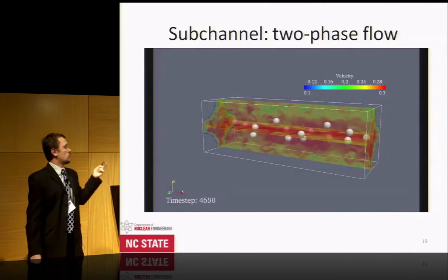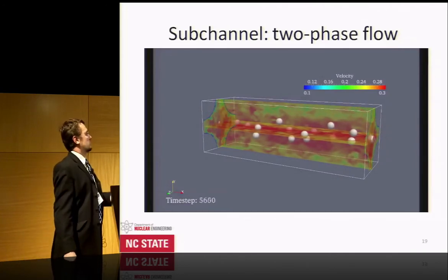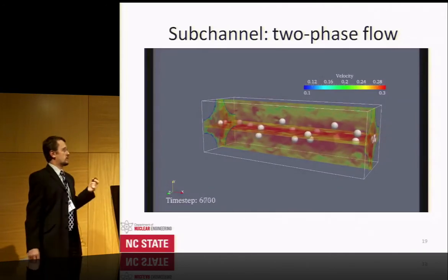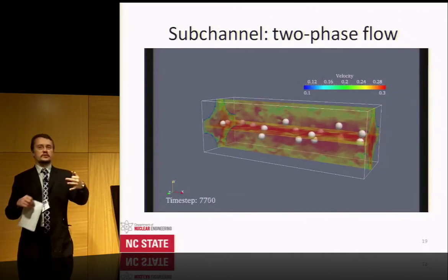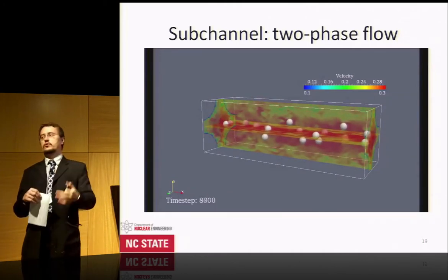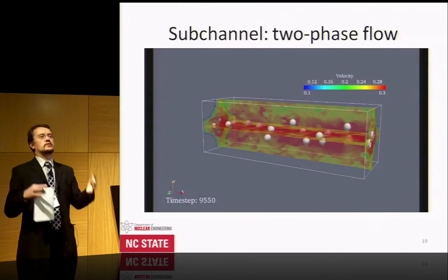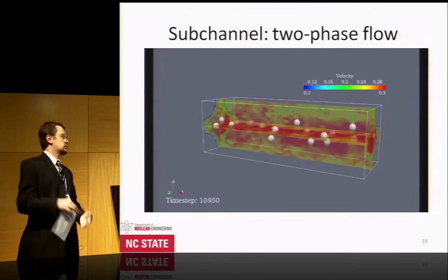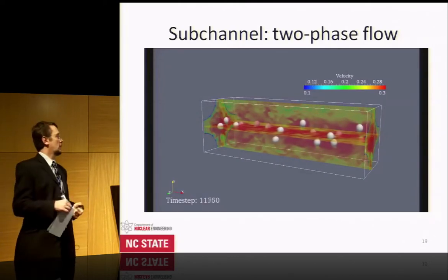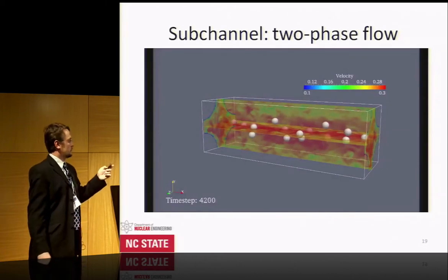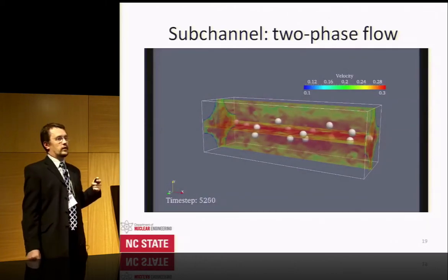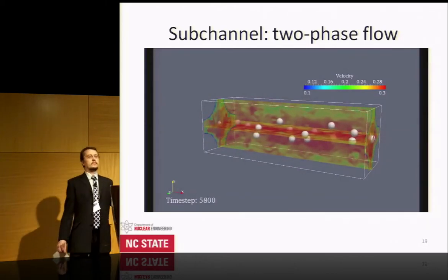Then we place the bubbles and we simulate the bubbles. We have somewhat different requirements. Again, you're restricted by the time step pretty heavily when you want to claim that you properly resolve bubble deformation, bubble coalescence, bubble-wall interaction, these kind of things. For this simulation, you have 17 bubbles, and this is the 50 million mesh.